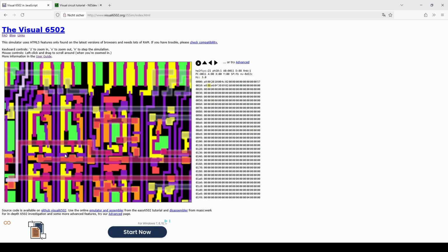Notice that this was off when we loaded x onto the bus, and now it's on again to refresh this. Right, and now it's off again, and now we're putting the value from the bus, which is 1, right, because we incremented 0 to 1, which sets bit 0. That now gets put back into the register. So this is now powered, which lets this 1 from the bus go through here,